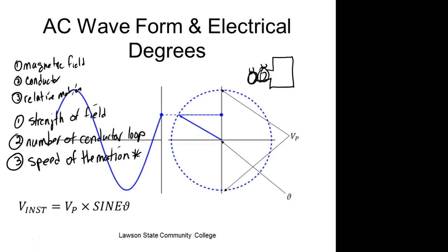But if you put your meter on there, it's going to measure a little over 14 volts no matter what you do, because it's got a regulator. If the voltage tries to drop, the regulator puts more current into the magnet, makes the magnet stronger, and puts out more voltage. If it tries to go up, what does your regulator do? It puts less current into your magnet, which causes the output voltage to stay the same.